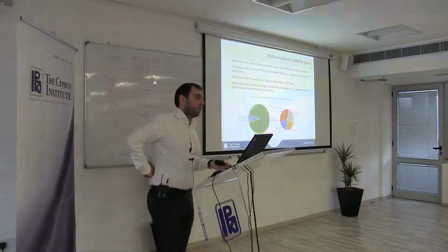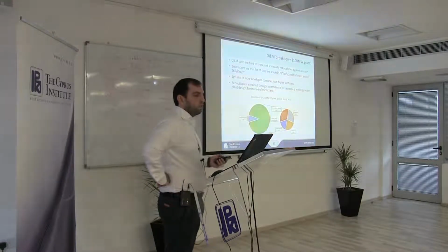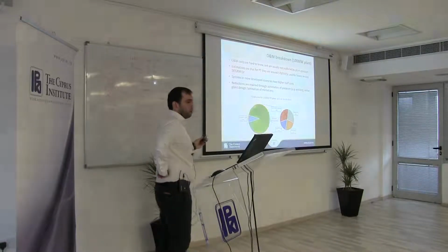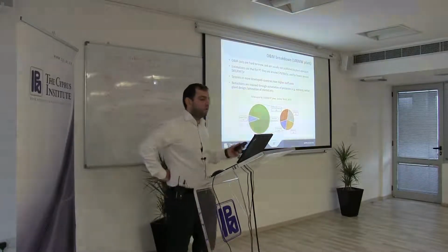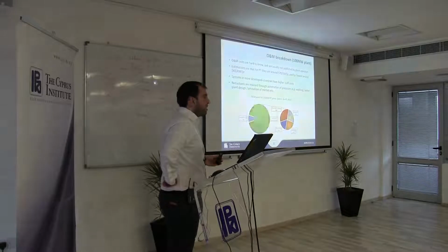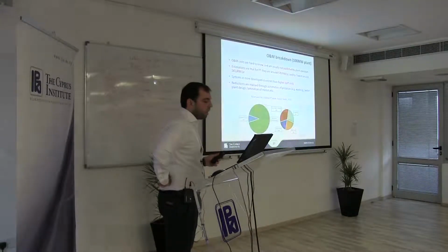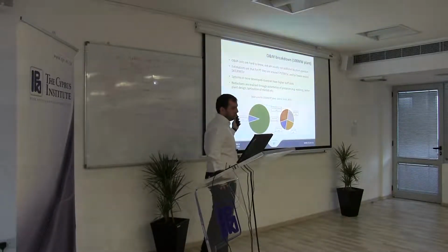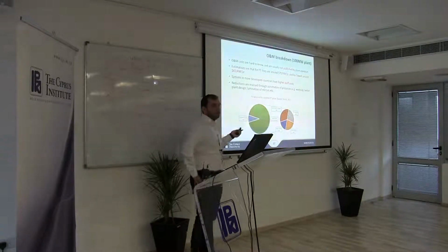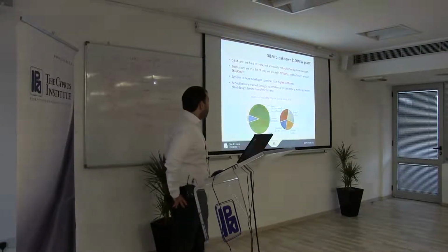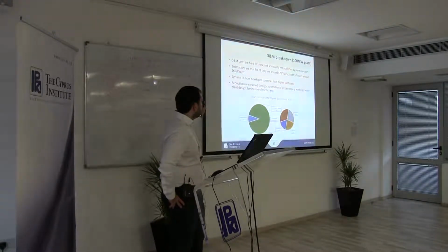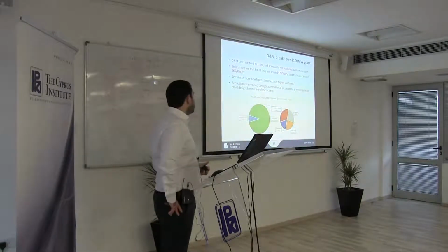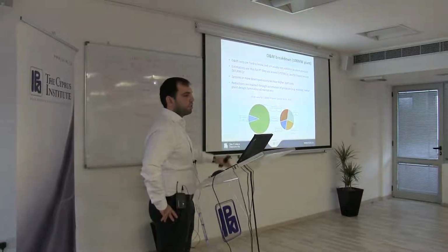The actual costs that are incurred by plant operators are not really well known because they're not published. They're confidential information. But the estimations show that for parabolic troughs, these are around $70 per kilowatt per year, while for towers, these are around $65 per kilowatt per year. And of course, in case of more developed countries with higher staff costs, the operation and maintenance costs would be proportionally higher. Reductions in these estimations can be realized through automation of processes such as washing, better plant design, or lamination of mirrors to avoid dust or soil from settling on them.